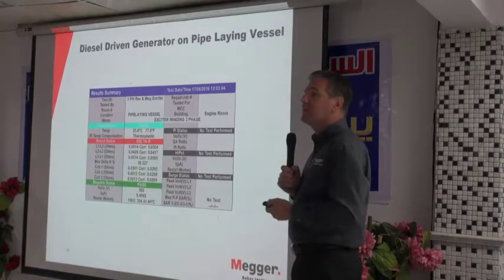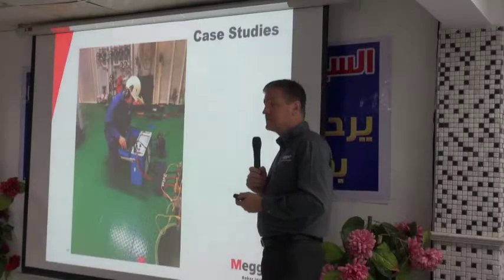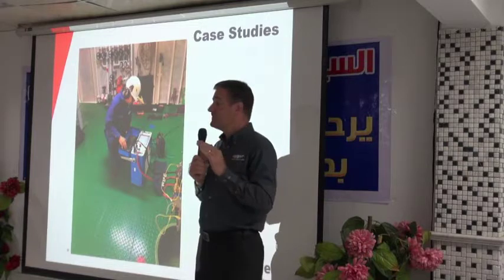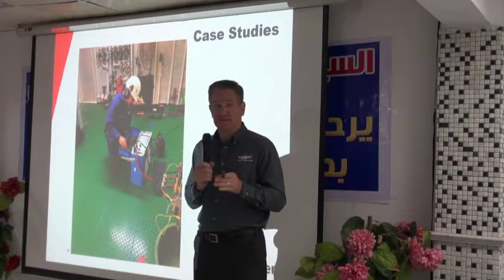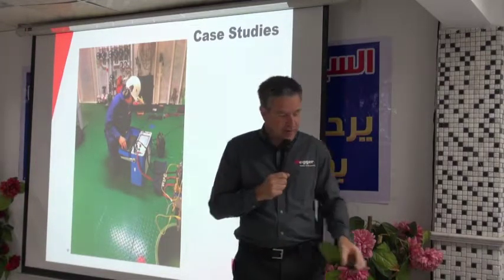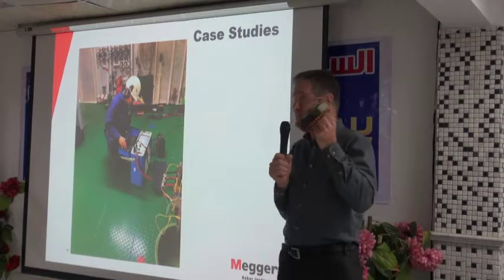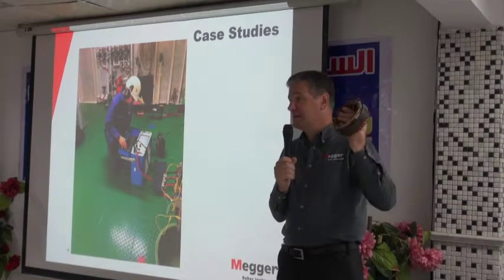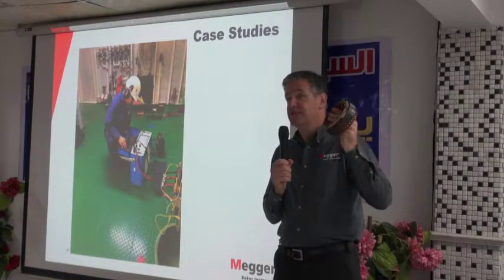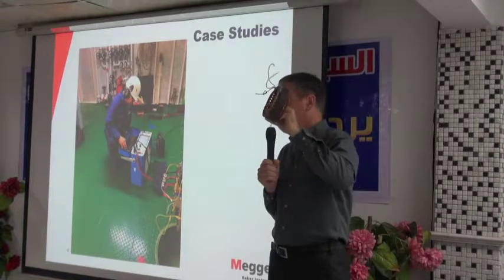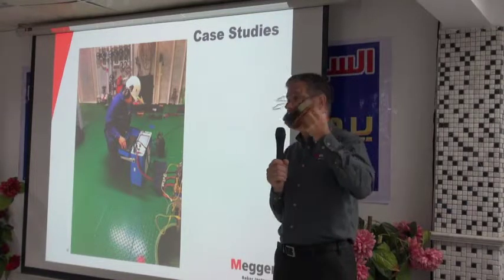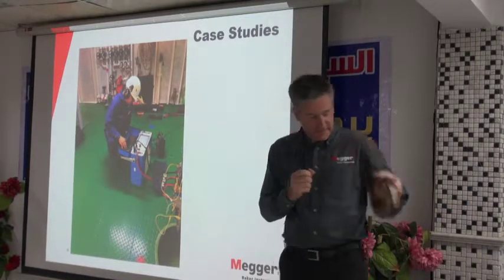By phase to phase, you mean a turn in this phase and a turn in this phase, right? Yes. And you can find a phase-to-phase problem with a megohm test. I agree. But your voltage has to be very high. Okay. I cannot find a phase-to-phase problem on my motor with a megohm test because my star connection is inside. I can't open the star connection. So if I make a megohm test on this motor, I have a short circuit. It's impossible. But I can make a phase-to-phase test with surge. So this is the difference.